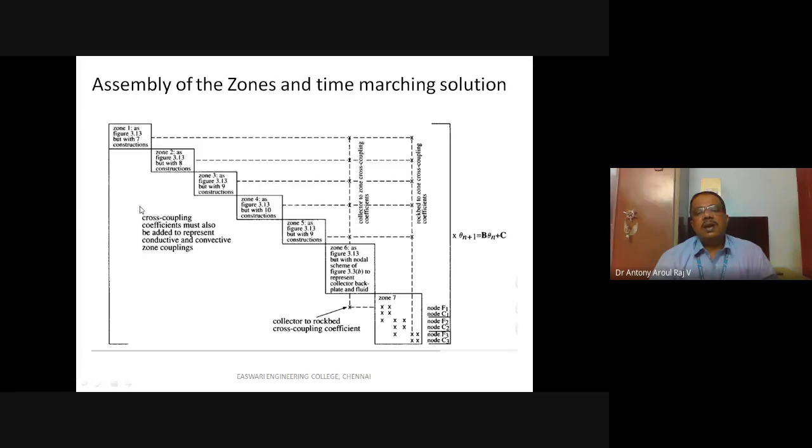Okay, here we will be calling it the thermal matrix, because in FEA you will be dealing with elastic materials, iron, and other materials. But here, these are all the building properties, the building properties matrix. For example, the thermal properties for a wall will be rho, Cp, K. Mostly these properties will be arranged in a tridiagonal form, one-dimensionally. So all these tridiagonal matrices will be appearing here.